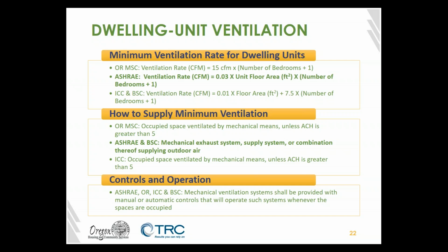It's continuously operating. And the only reason you turn off is because no one's home for a big chunk of time, or on some occasions there's some kind of outdoor event where the air quality outside is so bad that you don't want to be sucking that in. So that'll happen when there's a wildfire nearby. That'll happen in certain smog conditions in certain cities. But typically it's a 24/7, 365 running system of mechanical ventilation, and how you set that up for controls and automation.